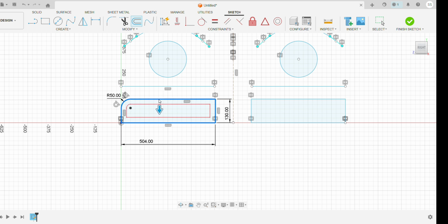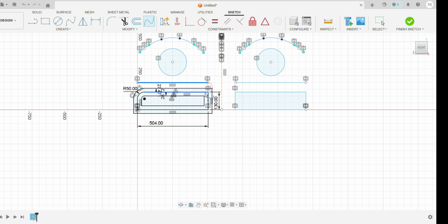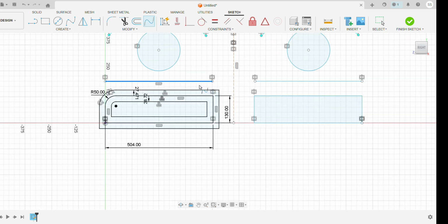Now this is the offset option. In the offset option, you can go offset inwards or outwards. It is generally used to make bracket kinds of geometries. Now this is also a kind of curve, so you can make some spline or curve like you are designing turbine blades.